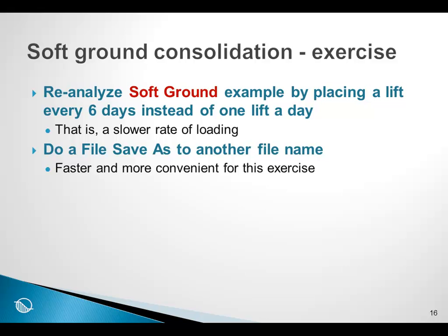Doing a File, Save As in this particular case is better than repeating all of the analysis in the same file. In this case, it's faster and more convenient. So once again, as an exercise, you can alter the duration for placing each of the lifts to 6 days, having then 6 time steps for each analysis, and then repeating the calculations, everything else being the same.